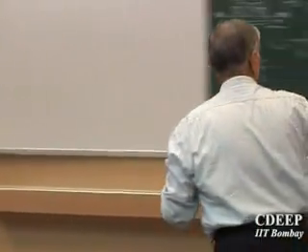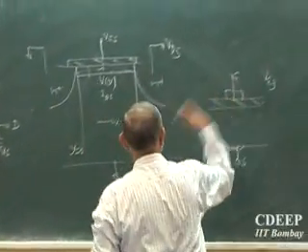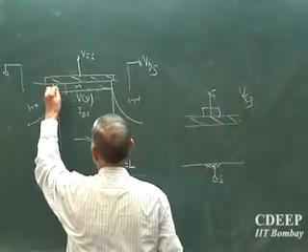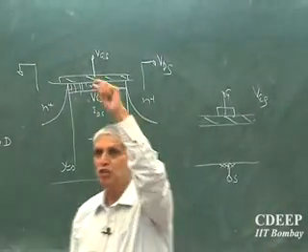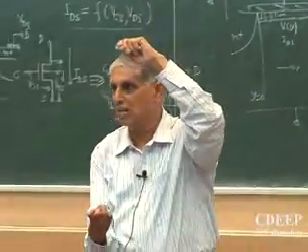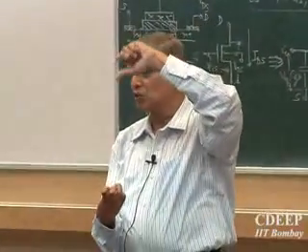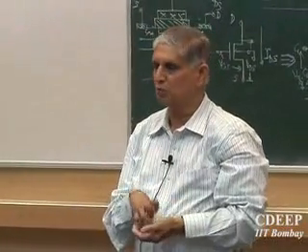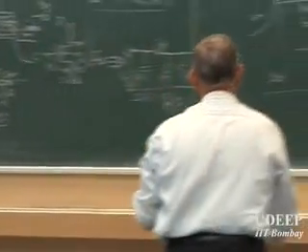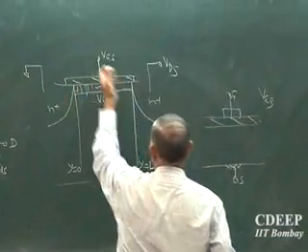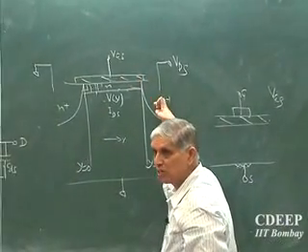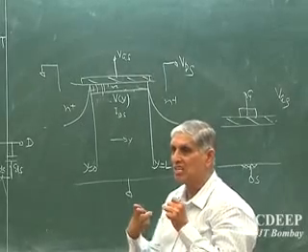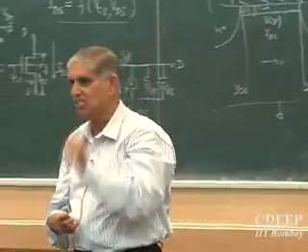Now this is different from a capacitor. In a capacitor, the same voltage is across all of it. But now at every point, Vg minus the substrate, which is now the channel, is different. Vg minus Vs is different everywhere. VGS is highest at the source end, because the channel voltage there is 0. But how much will it be on this side? Vg minus Vd. Now what is the condition of inversion? I said VGS, or Vg minus substrate voltage, must exceed the threshold.